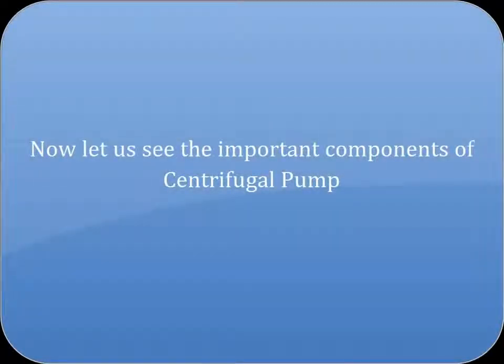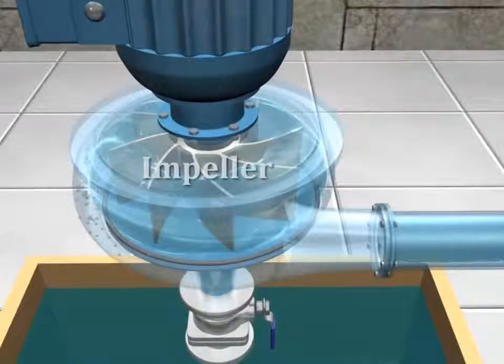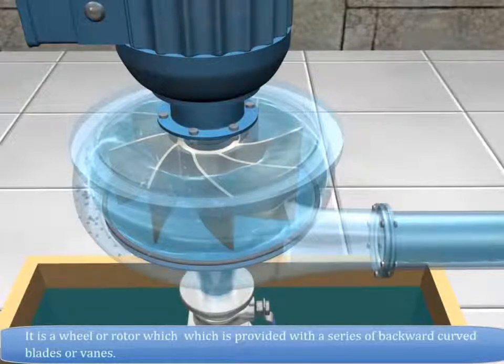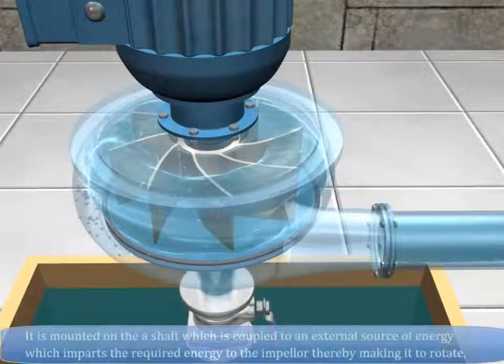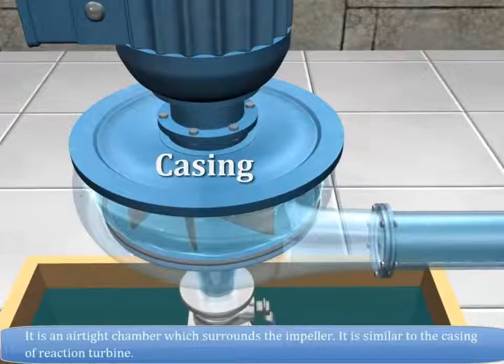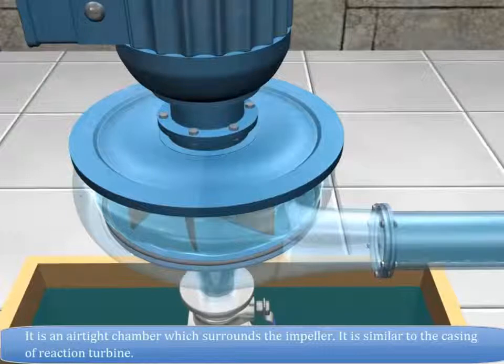Now let us see the important components of a centrifugal pump. Impeller. It is a wheel or rotor which is provided with a series of backward curved blades or vanes. It is mounted on the shaft, which is coupled to an external source of energy which imparts the required energy to the impeller, thereby making it rotate. Casing. It is an airtight chamber which surrounds the impeller. It is similar to the casing of a reaction turbine.